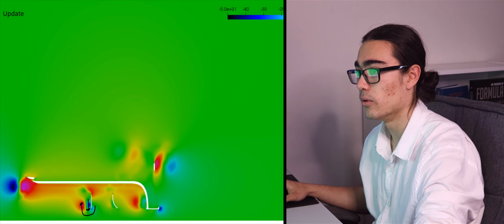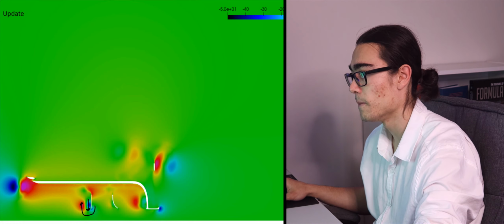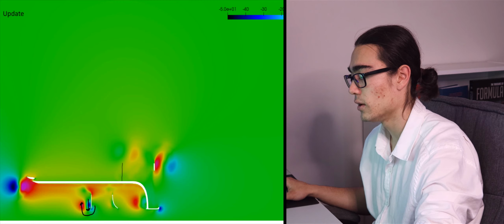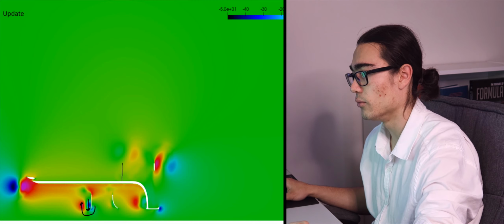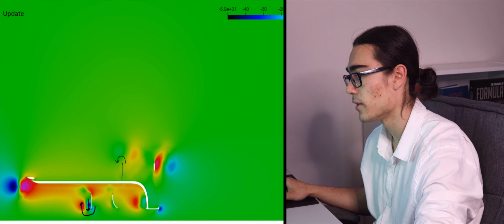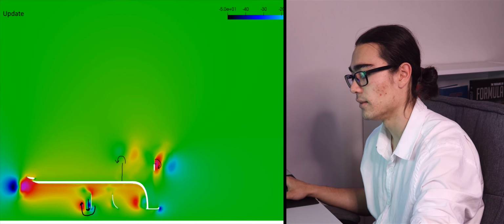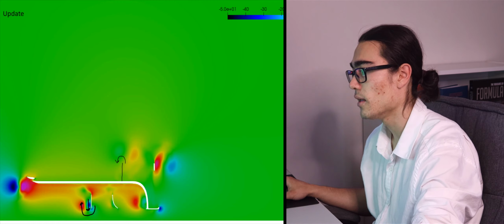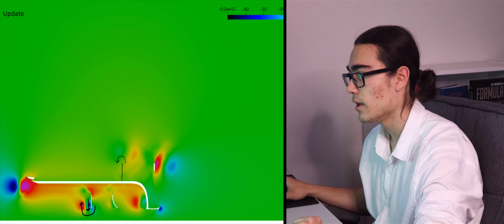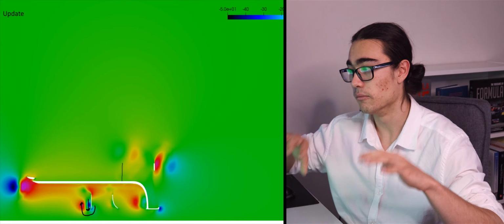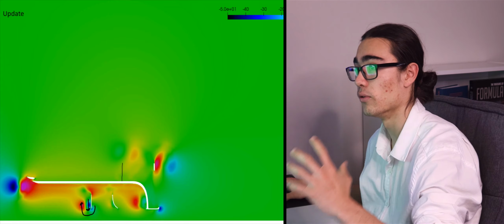Now, I'd say that one of the more important interactions that we're seeing here is what's going on in this region. So I'll draw out our geometry. We have a turning vane around about here, and we've spun up our vortices like this, and we had a canard coming out here, or a dive plane, whatever you want to call it, and we've spun up the vortex this way. So that should be a bit further out, sorry. But what we can now see is this counter-rotating vortex pair system that we've set up on the front wing.